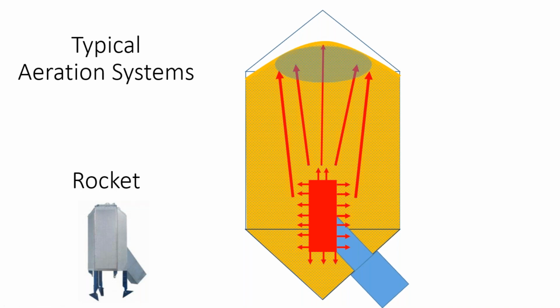Exactly the same as the Cube. You likely will get better drying in the core, so any fines will be a non-issue, and the drying front would likely look similar, where the bin walls would probably be drying slower than the core because of the excellent airflow through the core.